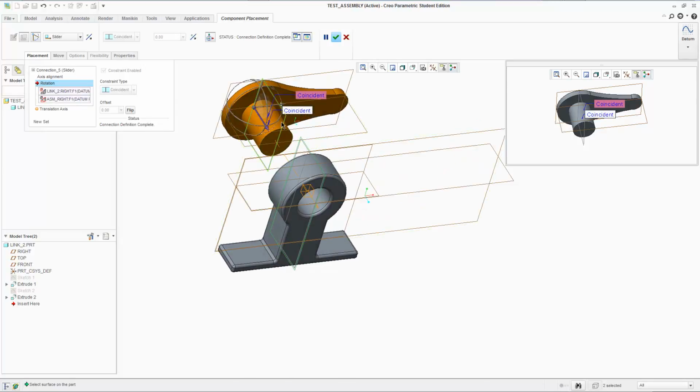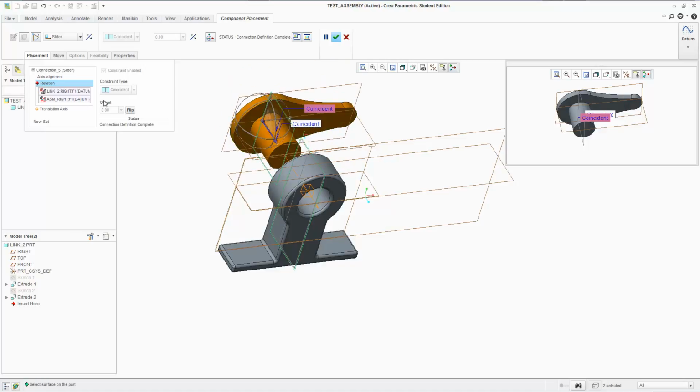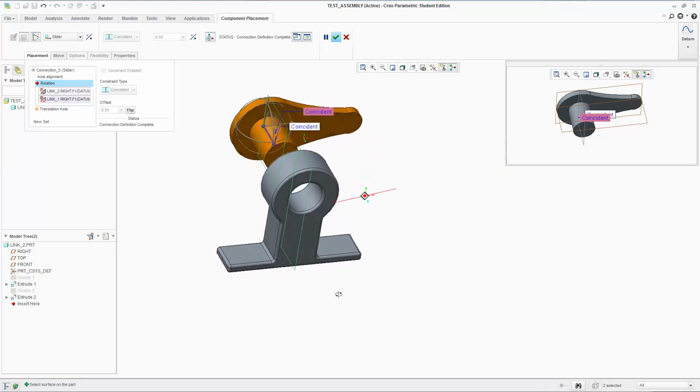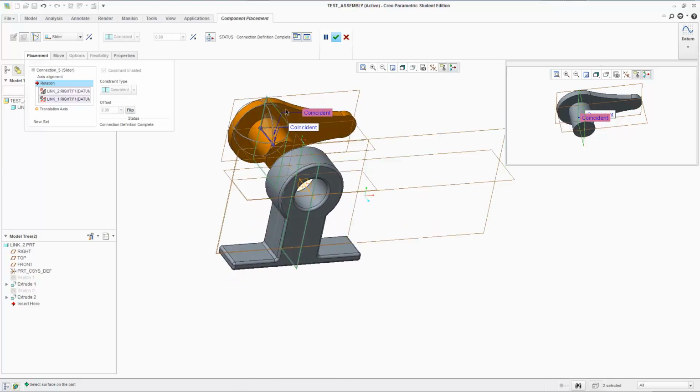It's gonna say I'm gonna remain coincident with this plane right here. What that means is, I'm not allowed to rotate anymore. I'm saying that this plane almost becomes rigid relative to this plane. And you'll notice that the rotational degree of freedom went away. Before, there was a blue arrow in the rotational degree of freedom indicator right here. If you watch again, it's allowed to rotate. But the moment I select that plane, it immediately goes back to a static thing that doesn't move in any rotation.